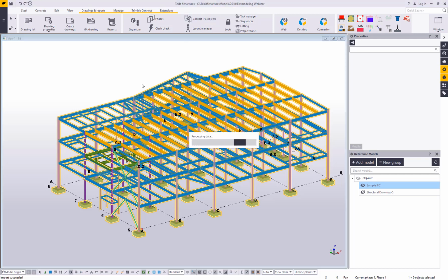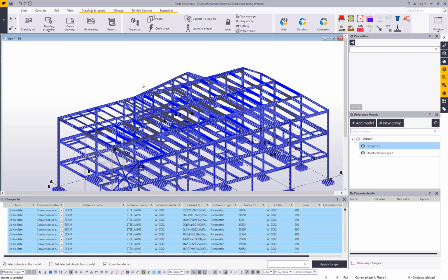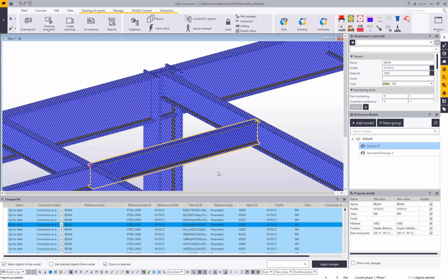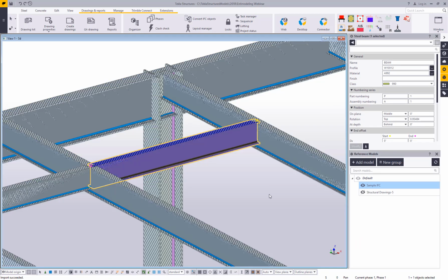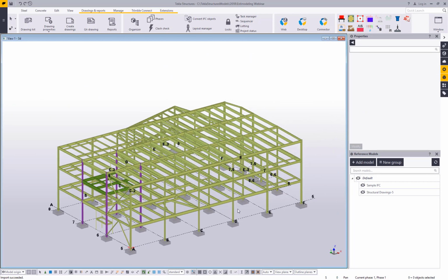And what this converter does is it looks at the size and shape under the hood and it says, okay, you were originally designed in the source software, wherever it was you came from, as a specific size, in this case a W10 by 12. Well, what do you know? We have a W10 by 12 in our shape catalog as well, so this feature builds the model for you. So that quickly now I've got the entire stick model created based off of the IFC simply by 2 steps: import, convert. And now I could run that material list again with a much more complete list of material.